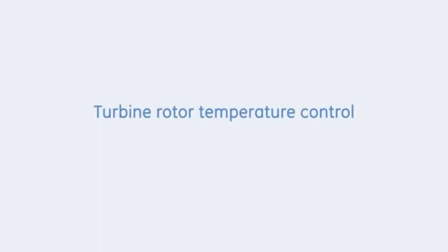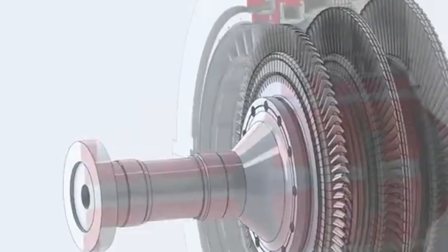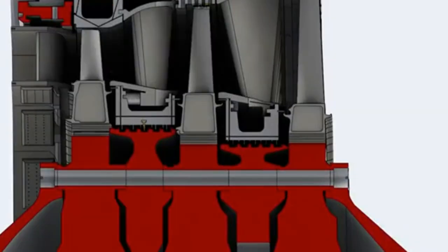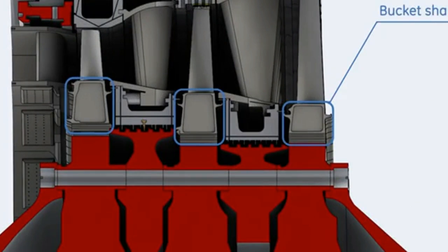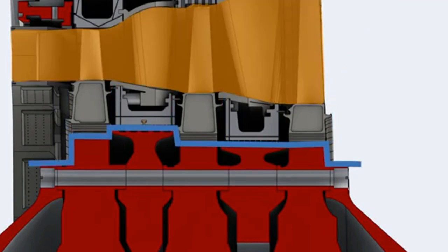The turbine rotor must be maintained at a reasonable operating temperature to assure a longer turbine service life. For this purpose, bucket vanes are not directly attached to the dovetail. Instead, they are connected to their dovetails by means of shanks. These shanks locate the bucket to wheel attachment at a significant distance from the hot gases. Combined with the diaphragm segments, this arrangement isolates the rotor away from the hot gas flow.